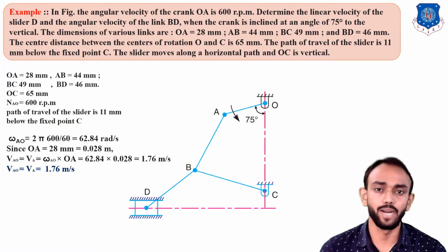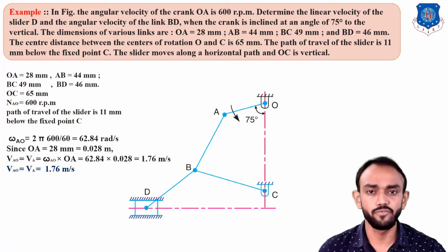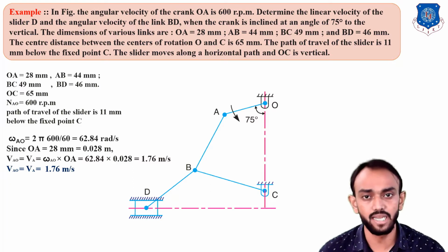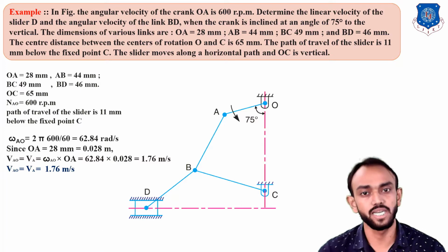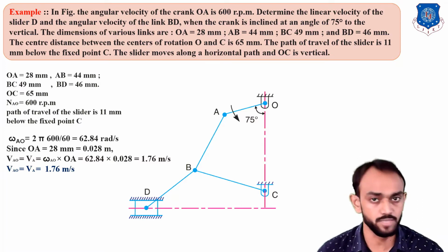Okay, I will remind you of the 4 rules of this chapter. First rule: all the fixed points in a space diagram will be at the same point in a velocity diagram. All will be at the origin point, because distance from the origin point indicates the velocity, and so all points which have zero velocity will be at the origin point.